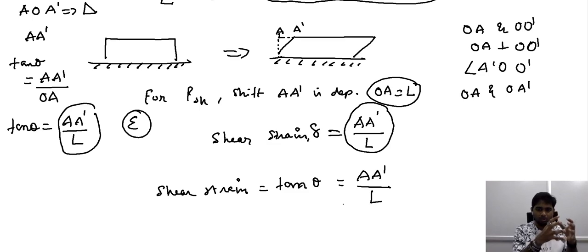So what we have done is, we have considered a new form of loading condition, a mechanical condition. How the material responds to this new form of mechanical condition is different from what we observe under tensile or compressive loading. In this case, there is no change in the longitudinal dimension along the loading direction, or in the dimension in the perpendicular direction. So no Poisson's effect, no change in the dimension lengthwise.